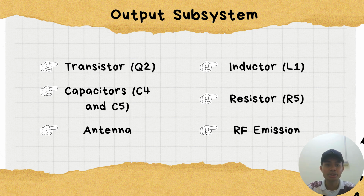The second one is inductor L1. The inductor, which is a component of the tank circuit, and C4, capacitor 4, are essential in determining the carrier wave frequency. It also contributes to the impedance matching between the transistor and the antenna in the output stage.